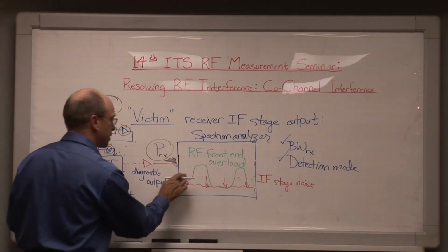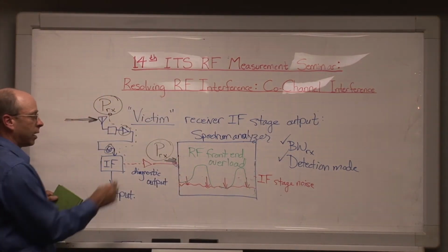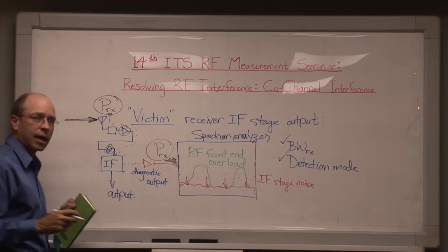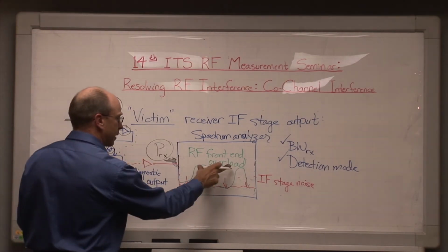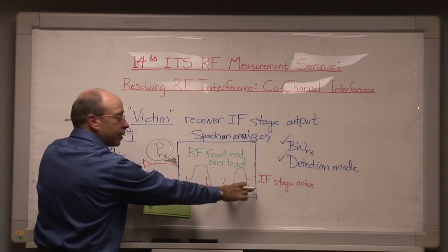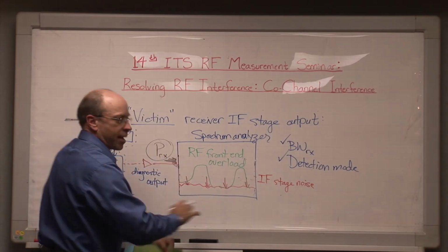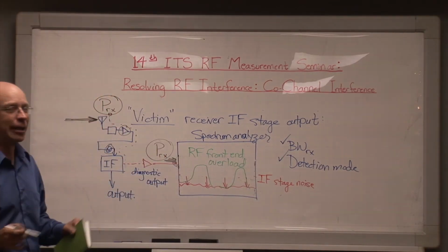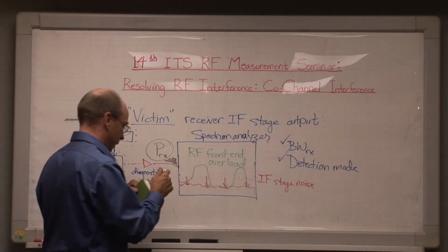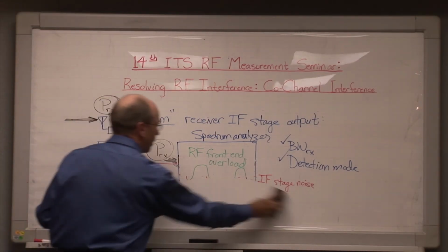In other words, you don't see interference occur, but when the receiver's performance drops out and it seems that interference is occurring, inside the receiver you see its noise floor drop down, and you see the desired signals either drop down or disappear entirely. That's RF front-end overload. And as I say, that's a separate problem.